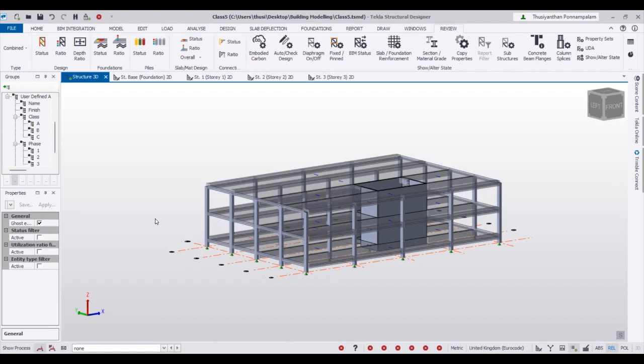The lateral load basically has two types we are considering. The first one is the equivalent horizontal load or notional load. This one is calculated automatically, so we don't need to calculate and input it. Wind load only, we have to calculate and input. I think most of you are familiar with how to calculate the wind load, right? I'm not going to go through it.